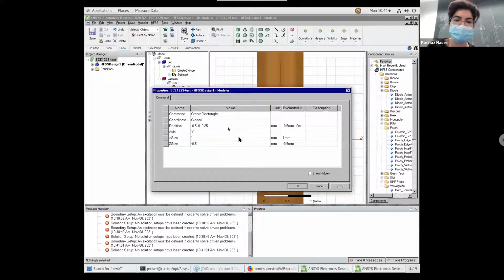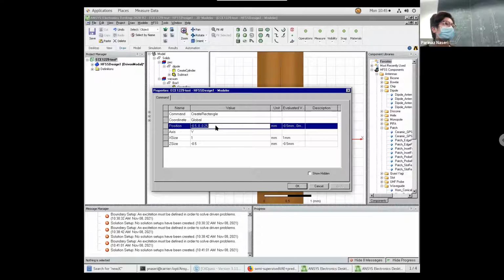Now, again, we do the same thing. Even though the parameters might look right now, we want to parameterize it, so in case we change a parameter, everything changes automatically. Okay, for this lump port, I'm going to go back to here since we only have white. I'll use this one. So the lump port goes from the center of this cross section, from here to here, right?